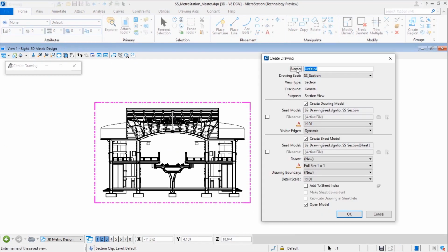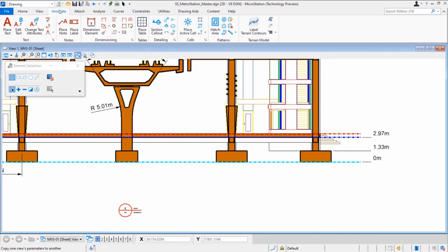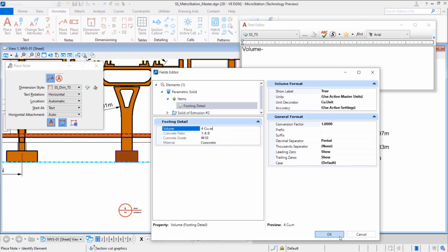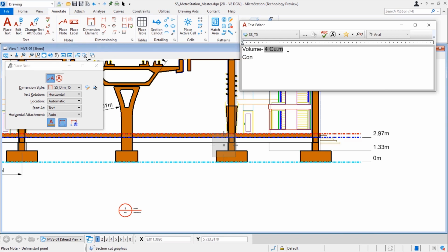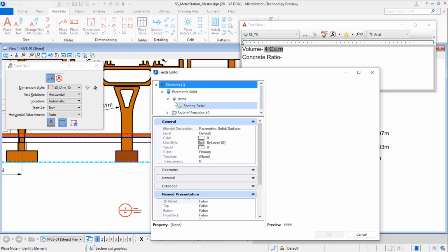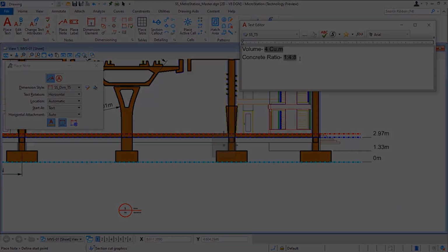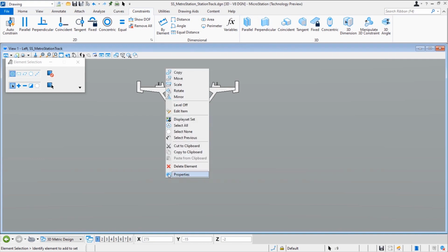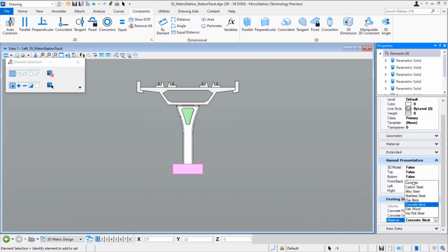When all your models or elements have been tagged, then creating drawings and managing annotation becomes very easy. You can see how these changes are automatically propagated to the annotations in your drawings. You can go back to your design and change sizes, shapes, or one of the specifications and not worry about having to manually edit all text wherever that was referenced.